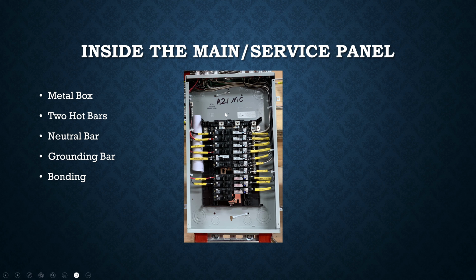So what's going to happen is that bond here is going to allow the circuit to be completed, and it's going to allow the electricity to flow from the hot. Oh, the hot touched the box of the dryer. Oh, that shorted the circuit. That closed the circuit. So now the power is going to run through your dryer box back into the ground, through all the ground wires back into this panel, and this jumper is going to say, okay, I'm connecting from the ground where that fault was, back to my neutral, so I'm finishing the loop, right? And you only want to do that here in the main panel so that it's a safety thing, and there's more you can learn about that later, but that's the basic thing that's special about the main service panel.